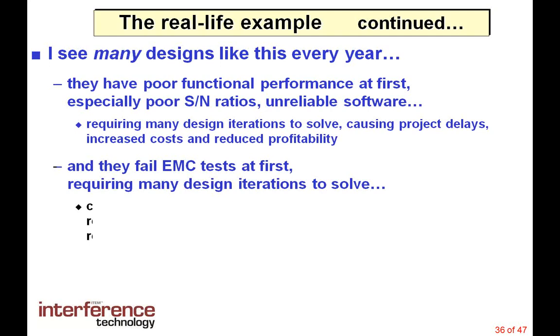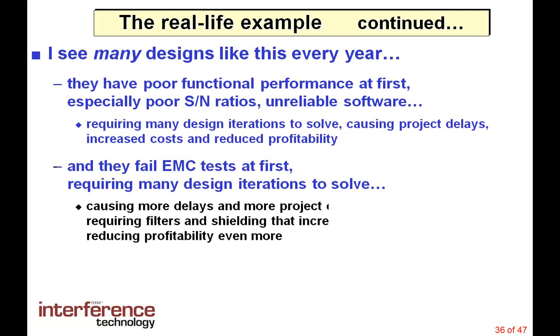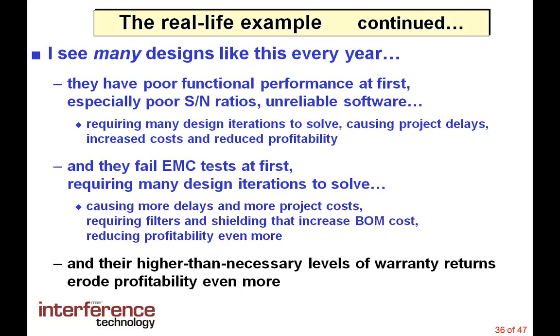And then, when they've got the functionality working, they do EMC testing, which they fail, and do more design iterations to solve, causing even more delays and more project costs, adding filters and shielding with increased BOM costs and reduced profitability even more. And they tend to have higher than necessary levels of warranty returns, which erodes the profitability of the product line even more.